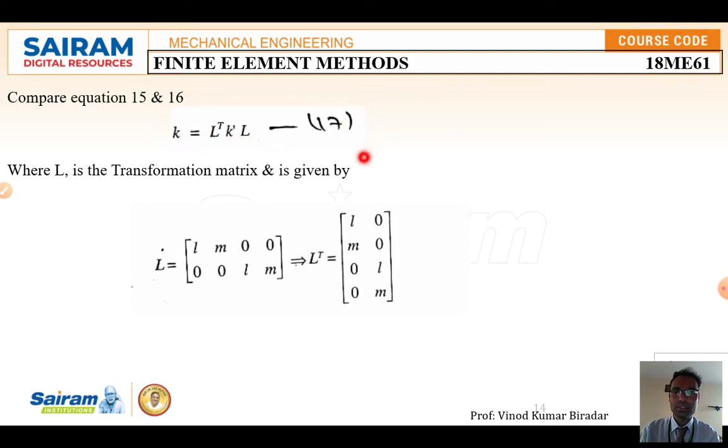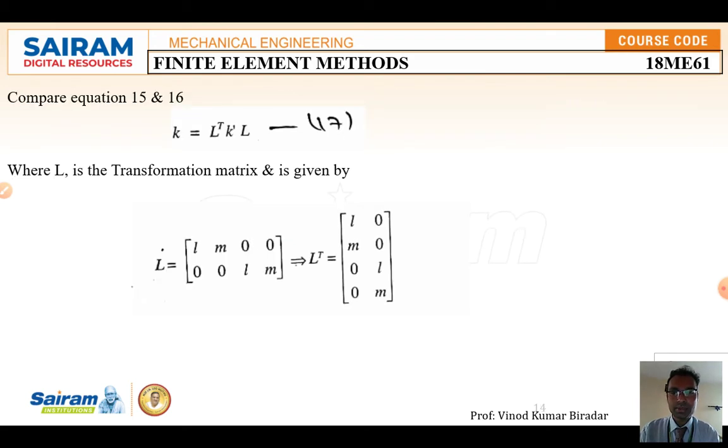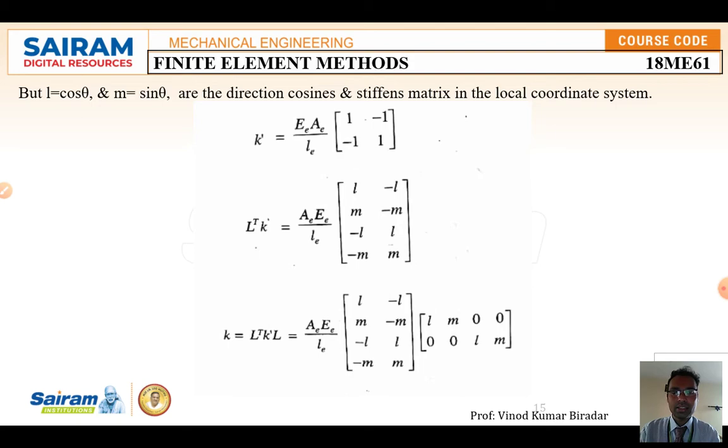Give question number 17, where L is the transformation matrix, which is given by this, already we know this. So L = [l m 0 0; 0 0 l m]. The transpose of this is nothing but its transpose. We know that l = cos theta, m = sin theta are the direction cosines, and the stiffness matrix in the local coordinate system for this bar element is k' = (AE/L) [1 -1; -1 1]. So that transpose you have to write like this matrix: l m -l -m...